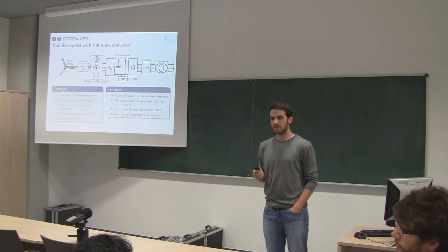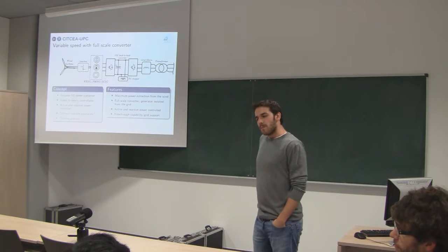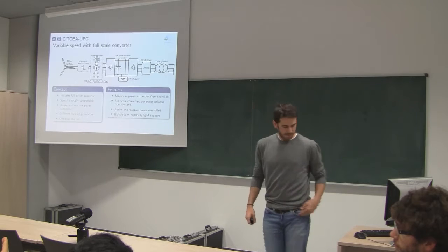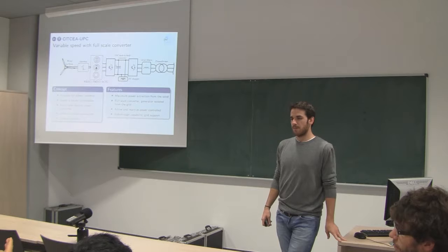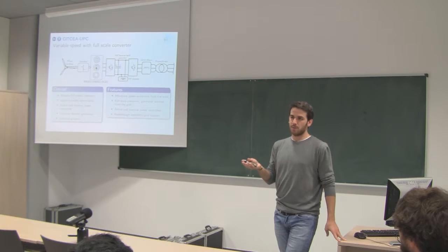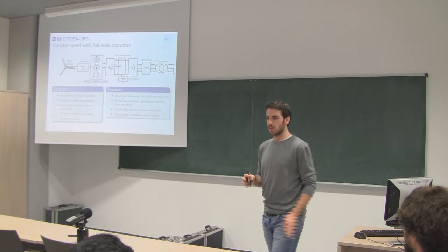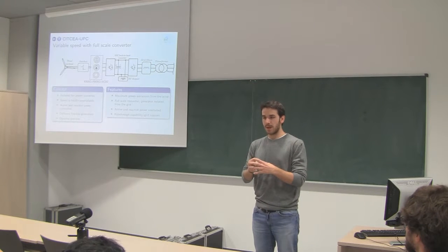I have a small question about the fact that the blades can rotate around their axis. Is it to keep the rotational speed constant, or is it to keep the power constant? No, this is called the pitch. It's called pitch or stall. What is used nowadays is the pitch control of the blades, as you say.